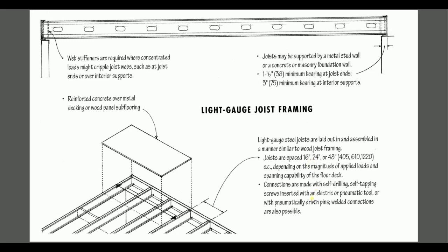Spanning capacity of the floor deck. The connections are made with self-drilling, self-tapping screws inserted with electric and pneumatic tools, all with pneumatically driven pins. Welded connections are also possible. So welded connections, sometimes we need the welding connections.